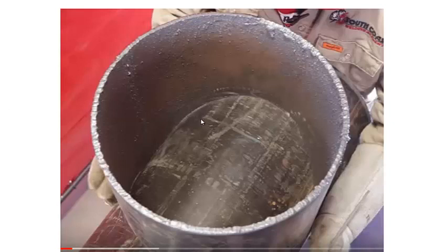Yeah, this one just shows that, see, he hasn't cut the cutout in the header. He's using the branch to lay out that header cutout. So he'll come in here and mark this ID where that branch sits down on that header. Then he'll go and mark the OD. And then he'll probably leave that line on the OD when he cuts. So I just wanted to show you that. This is a realistic way that I would use my branch to lay out my header. But I'm going to show you both.